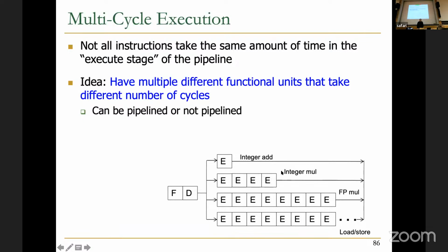However, you can pipeline your multiplication such that you reduce the clock cycle time and can work at a higher frequency, which is good for your performance. So we usually also pipeline our ALU, and in modern processors, the ALU is heavily pipelined.